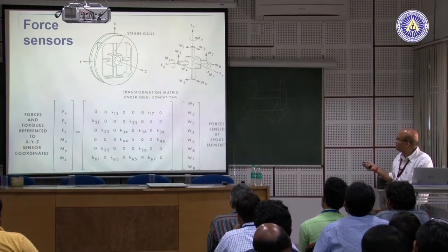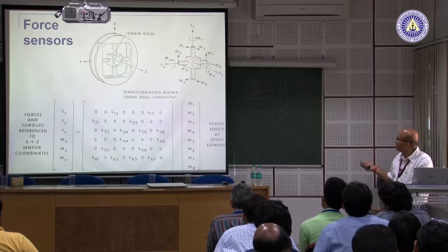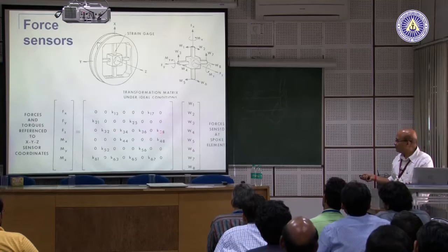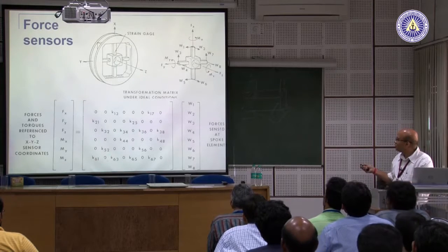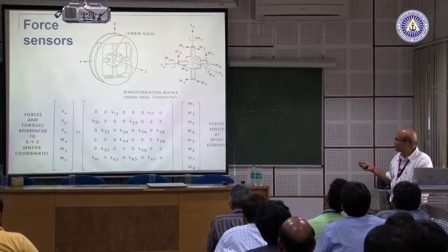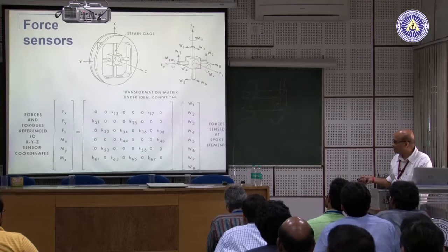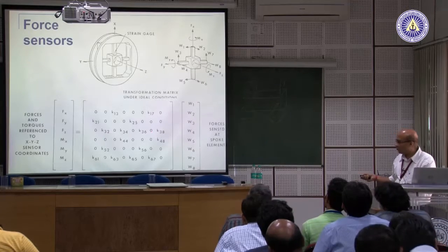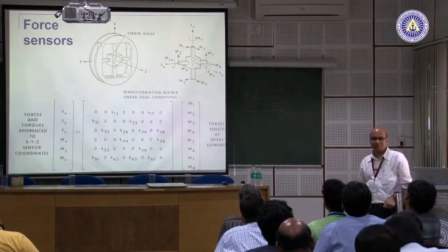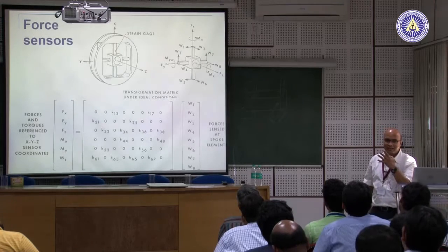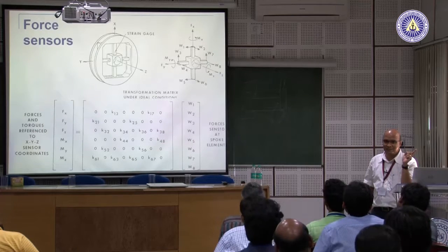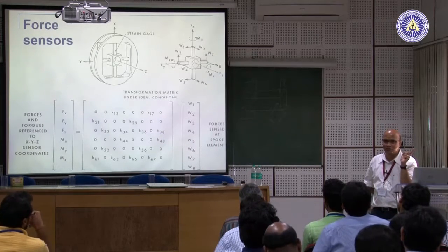Second problem is that if you look at the Fz, where is Fz? Fz is this side. So, Fz has reactions by this one, that one and that one. There are 4 of them there. Similarly, if you look at the moment z, so moment is like this, right. So, this moment is caused by this one, and that one. 4 components are there. You might say, so what? It basically means that any combination of these 4 can cause that equivalent force. Any linear combination of these 4 can give you the same result, right. Now, that is a problem, because you will not be able to differentiate your force now.